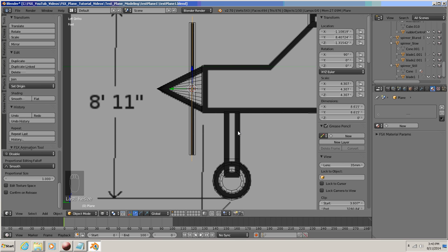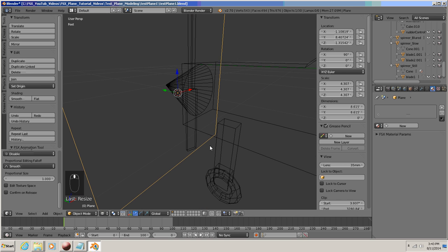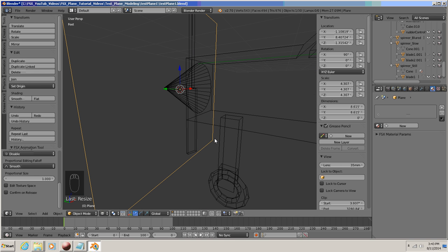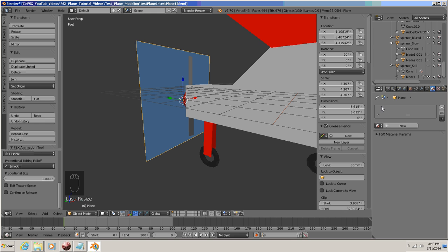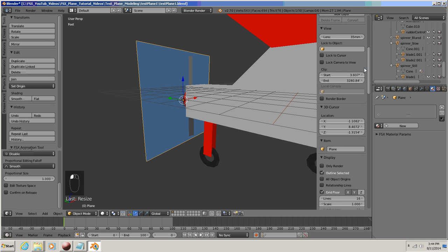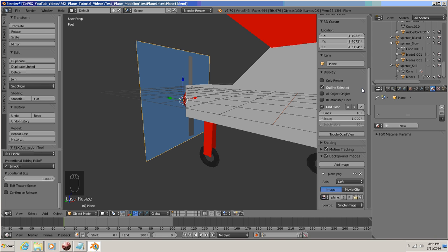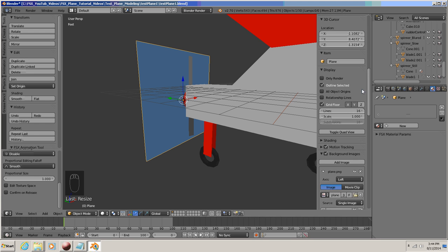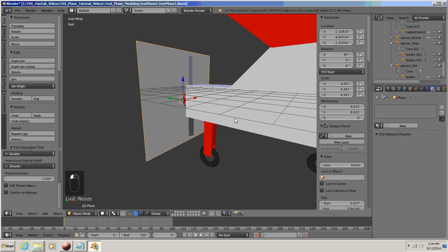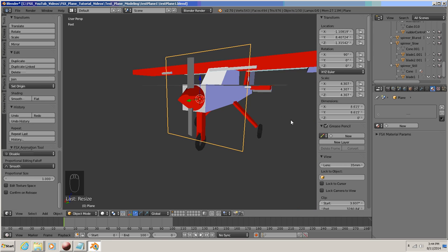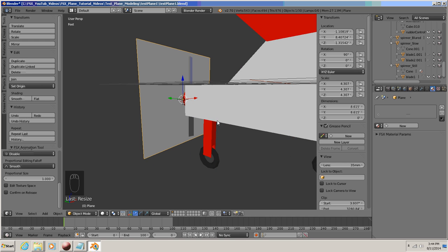We're now going to hold down the middle mouse button and go in perspective mode. We're going to hit the Z key on the keyboard to go into solid mode. Okay, we should not be able to see on both sides of that, so we're going to fix that. On the right side toolbar, if yours is not being shown, click on the little positive. We're going to scroll down to shading, and click textured solid. And we can scroll back up. Now if we turn it perspective mode, you can see the face there, but no faces there. That's what we want to see.